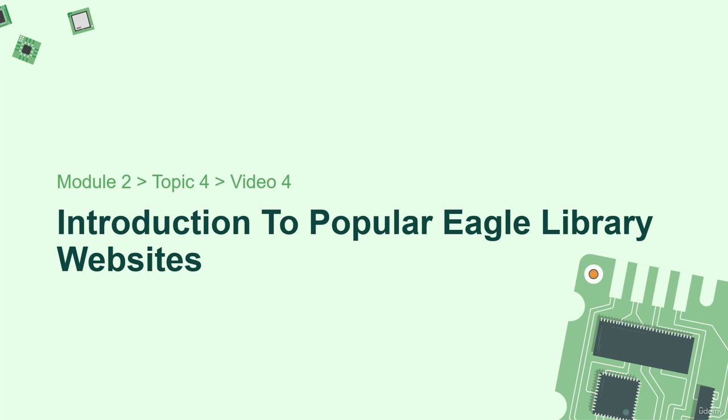Along with that, library creation is basically a very slow and tedious process, okay? And during this process, you can make a lot of mistakes, and we don't want those mistakes to reflect in the PCB, okay? So the better solution is to go to a third-party or online Eagle library website, and from there we can download the readily available library which was created by other people, and then we can install that library in the Eagle software.